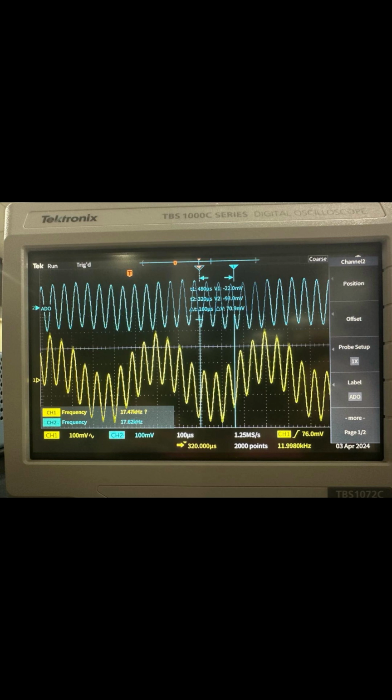We clearly see that the blue wave is a pure sine wave but with some noise, and using the measure function on the oscilloscope, we see that the frequency shown here is 17.62 kHz, which rounds to 18 kHz, considering some elements of lower frequency. Clearly the sinusoids can be compared, and we are assured that the differentiator circuit has given the proper output.